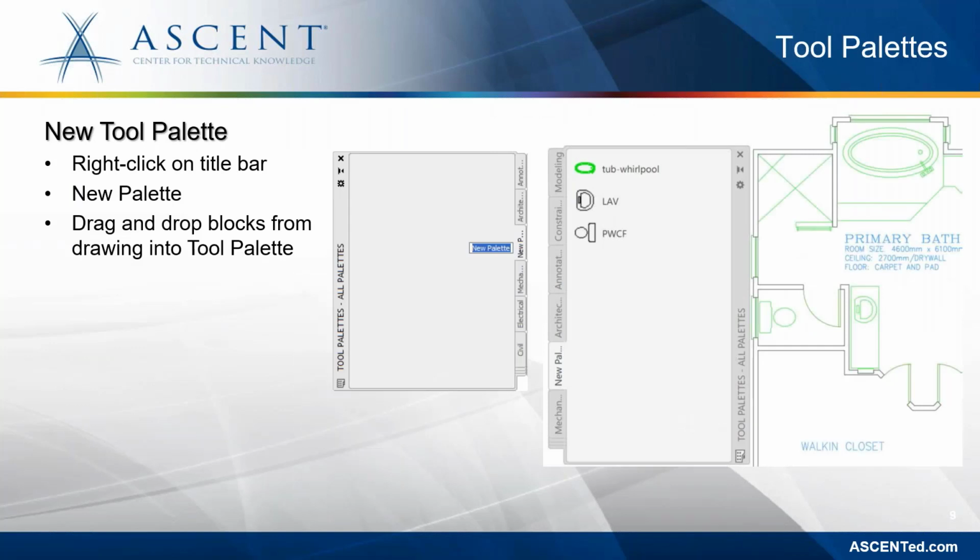Now let's see how to add block tools into the tool palettes. Tool palettes are one of the easiest ways for inserting blocks into a drawing. You can create custom palettes in the tool palettes to organize your blocks into logical categories. To create a custom palette, right-click on the tool palette's title bar and select the new palette option.